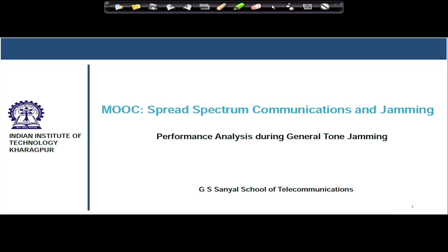Hello students, in continuation of the last module, we will now consider the performance analysis with respect to general tone jamming. By the term general tone, what I mean to say is that the jamming signal is considered to be present anywhere close to the center frequency of the intended signal transmission, which is equal to Fc. It need not exactly coincide with Fc. It is any general tone or any general carrier frequency where the jamming signal is present.